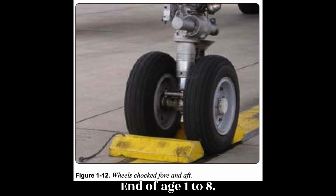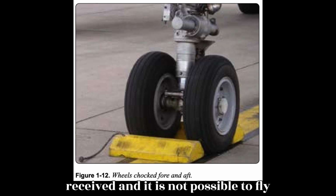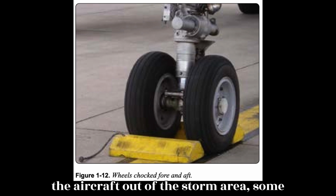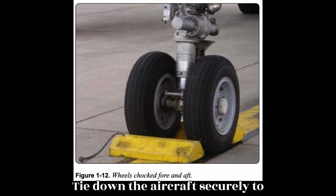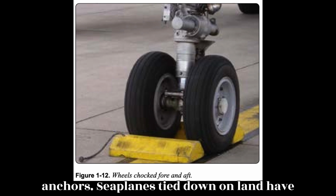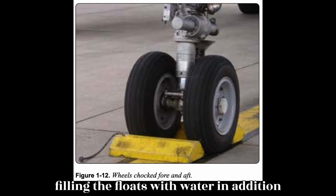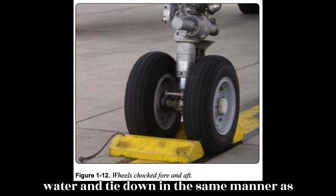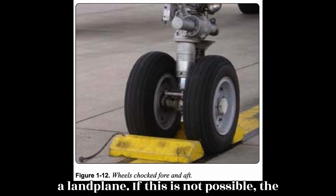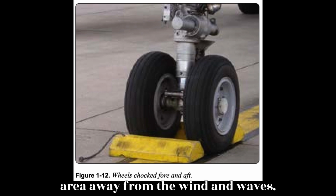End of page 1-8. When warning of an impending storm is received and it is not possible to fly the aircraft out of the storm area, some compartments of the seaplane can be flooded, partially sinking the aircraft. Tie down the aircraft securely to anchors. Seaplanes tied down on land have been saved from high wind damage by filling the floats with water in addition to tying the aircraft down in the usual manner. During heavy weather, if possible, remove the seaplane from the water and tie down in the same manner as a landplane. If this is not possible, the seaplane could be anchored in a sheltered area away from the wind and waves.